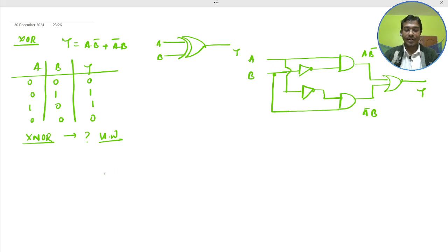So next one, the NAND gate as the basic building block. Any logic gate can be constructed by using only the NAND gate. First one, NOT using NAND, you have to construct this type.